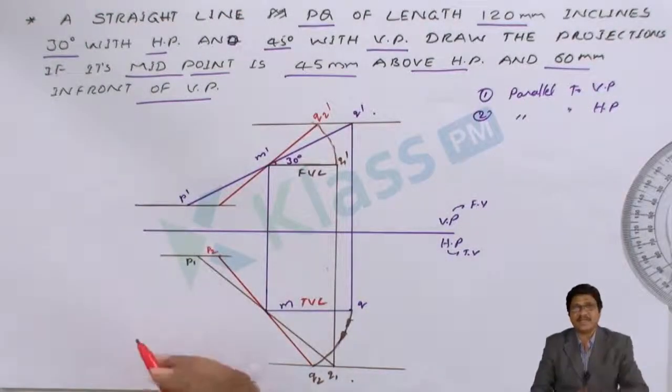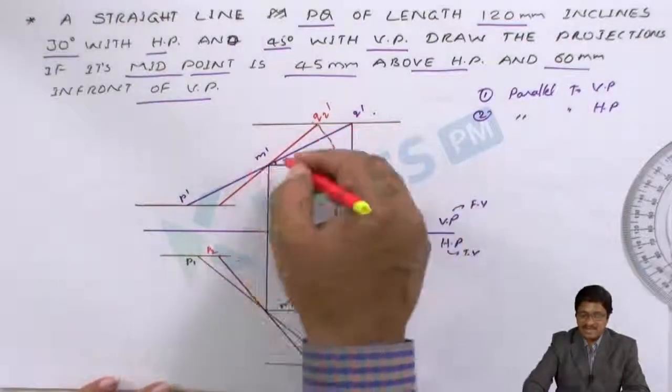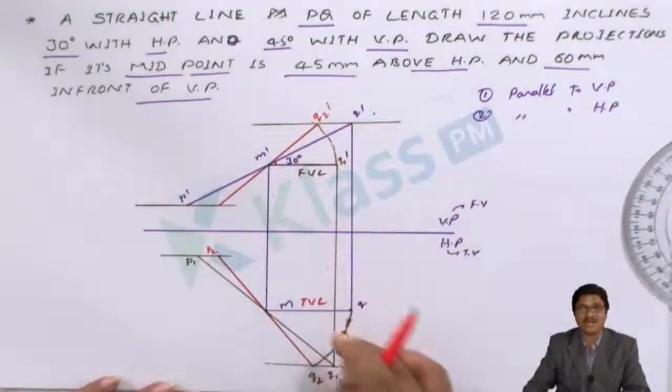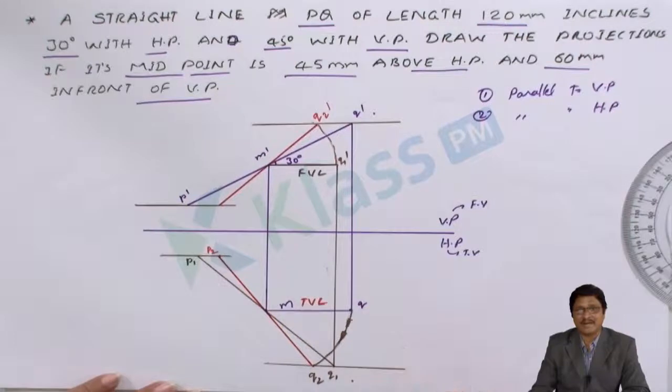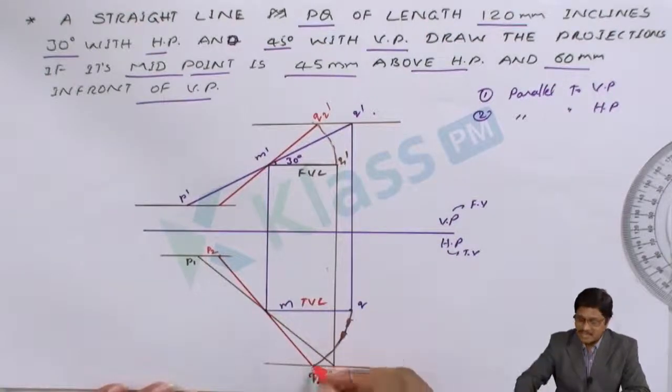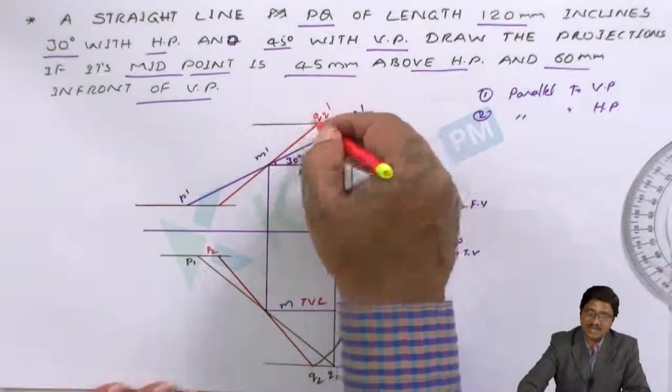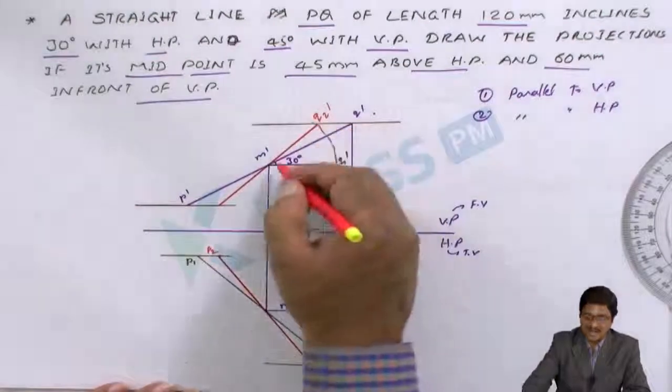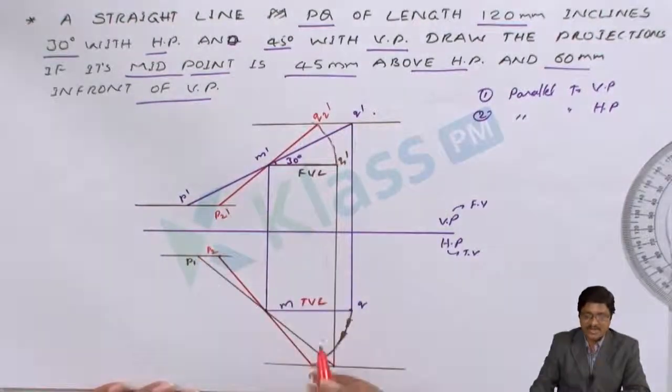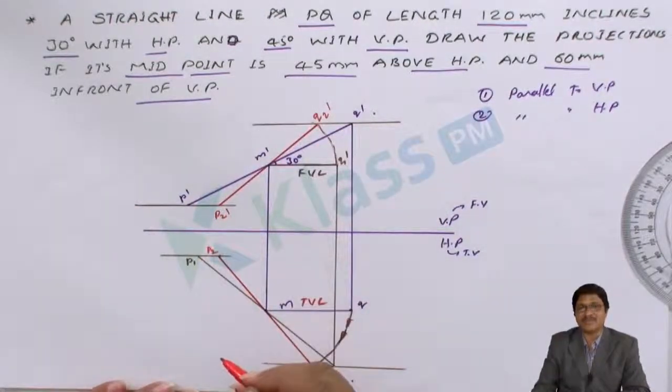So that's why in the examination, if there is any error in these stages, you may not align perfectly. So for that one, you could do the right way. Just do any one of the views. We know the fundamental concept: front view and top view are always in the same line. So from the Q2, draw a line until the locus line. We can mark that as Q2 dash. Just connect. Where you are getting is the P2 dash. So like that you have to proceed to represent the solution.